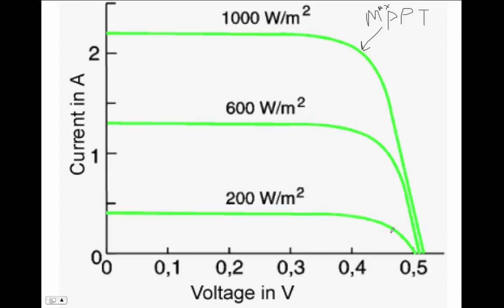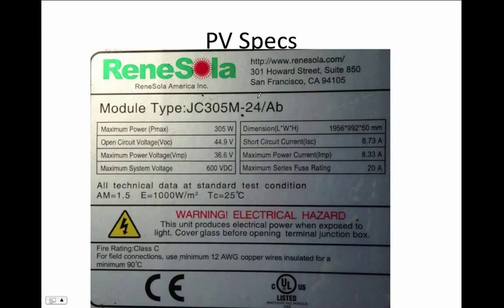In other words, if you have a solar panel that is operating at 1/5 the full amount it would get on a sunny day, on a cloudy day it's going to put out its full voltage, but its current is going to be limited. So the current you get is directly related to how bright the sunlight is, and the voltage pretty much stays the same.